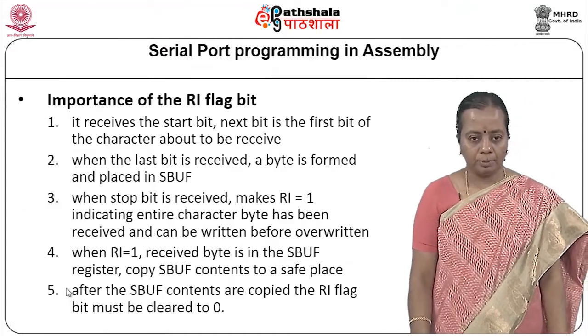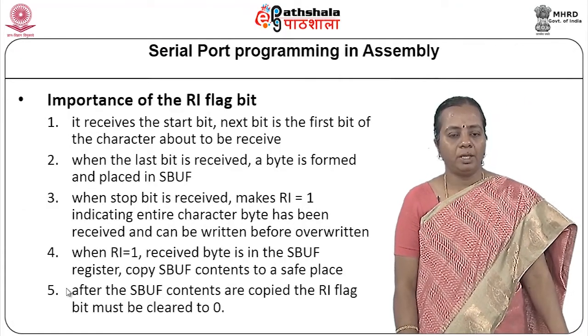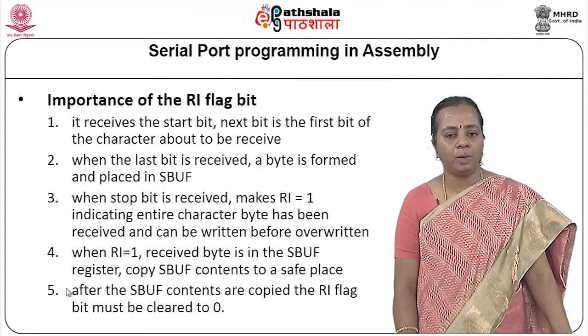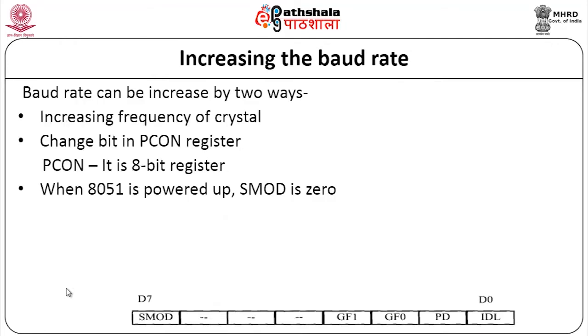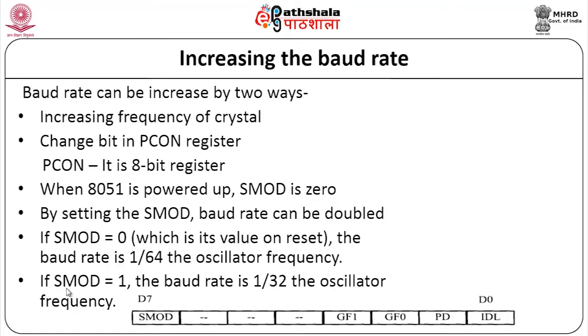Serially from outside. Without the RI flag we will not know whether we have received the data completely from outside. Now remember the baud rates we look at. Sometimes we need more than that speed, and for that reason they have provided a register called the PCON register. This is the structure of the PCON register, where if I set the SMOD bit to 1, the baud rate we are using is doubled compared to the previous case.